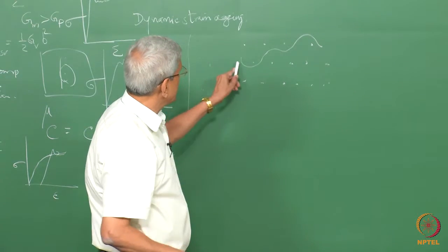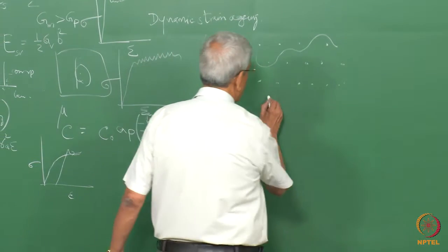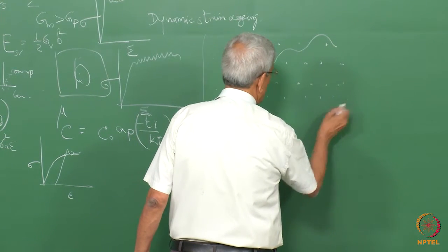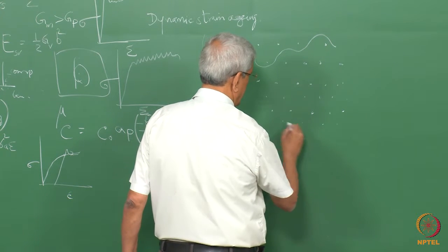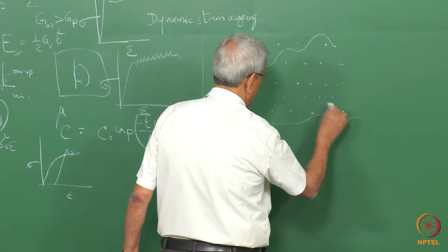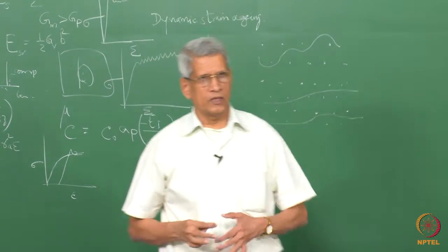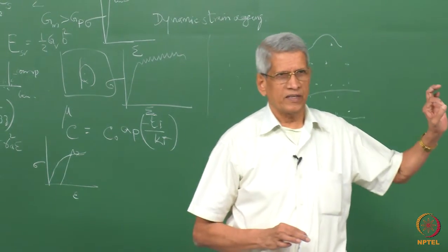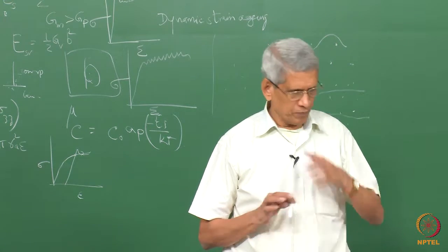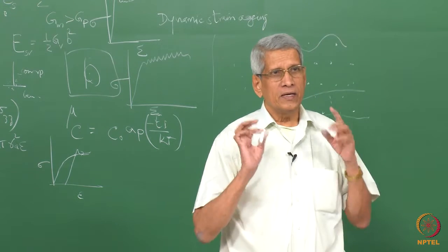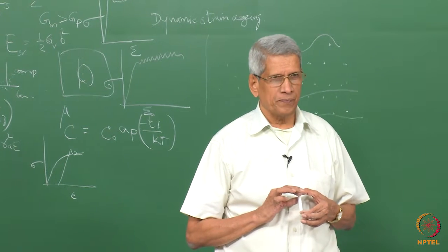This means essentially there is a local variation. The other way in which it can happen is that the dislocations are present, and here it is not interacting particularly with any one defect, but the effect of that defect has a long range interaction, correct? That is, the interaction is essentially a long range elastic interaction.